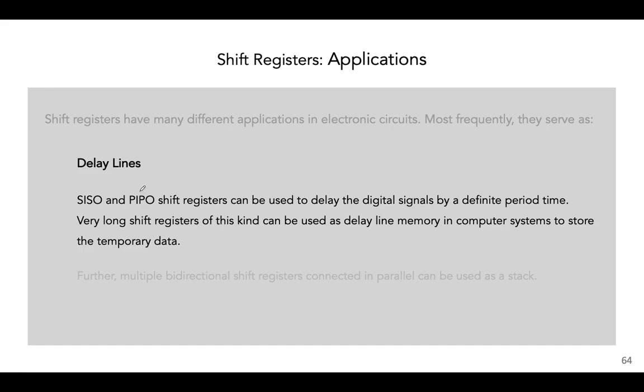The point is, before the data comes out and after it goes in, right, that period in between when the data is loaded into a register but it is not taken out yet, that is the part where the register is storing your information, and the output of the data is controlled by the clock pulse.